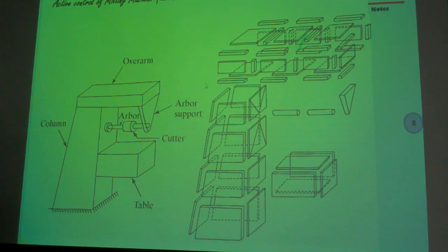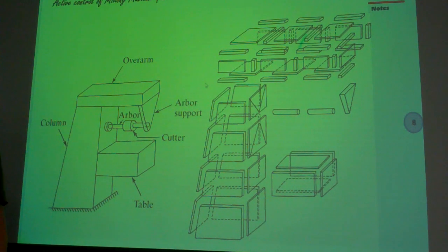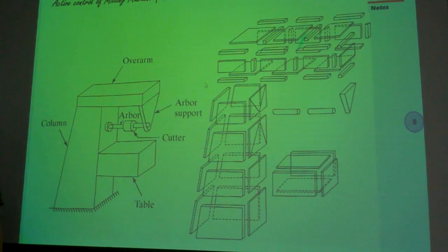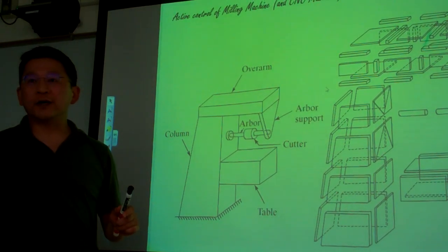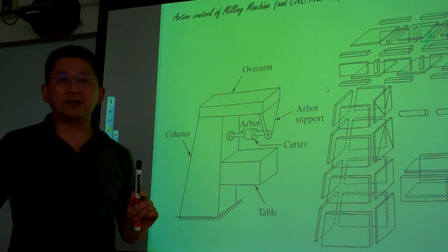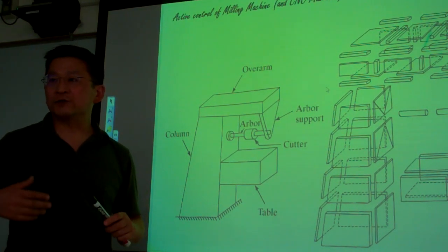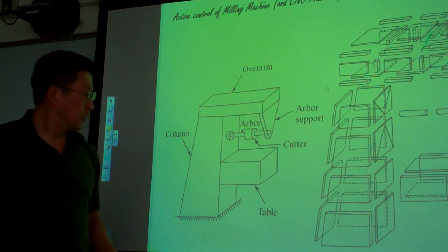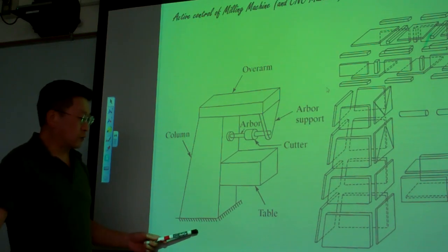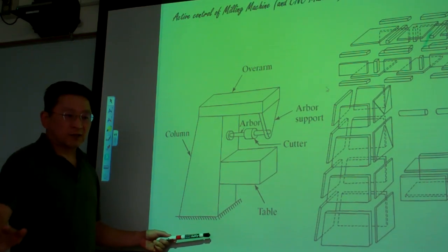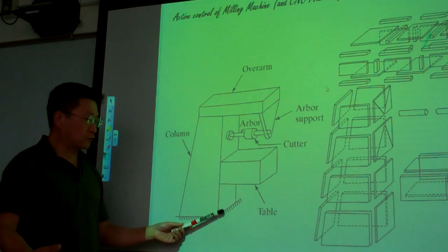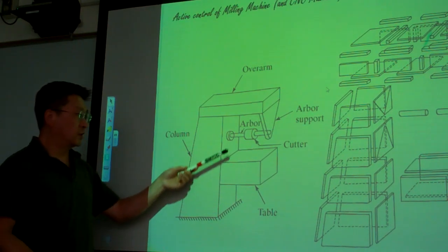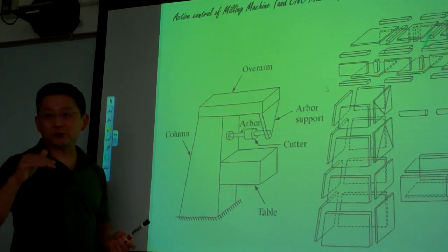So if they want very high precision of the machined components, one way to do it is to reduce any system-induced vibrations or system-interacting vibrations. That means you have to make sure the vibrations from the ground, or any motion from the ground transmitting to the machine, should be reduced.